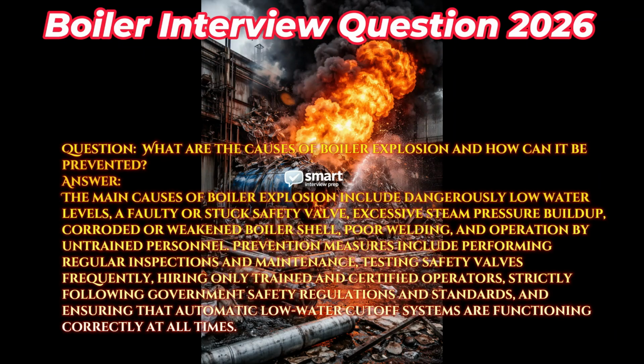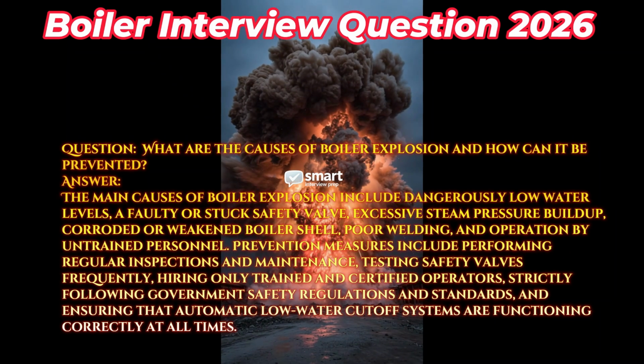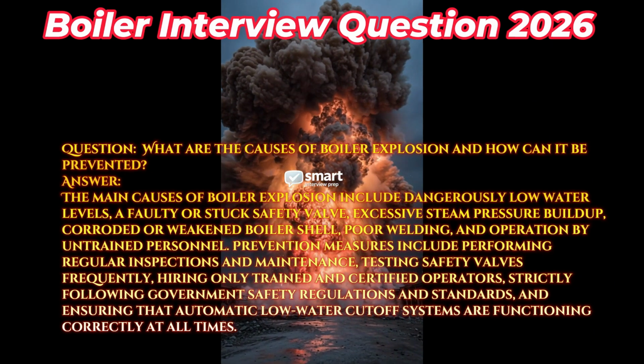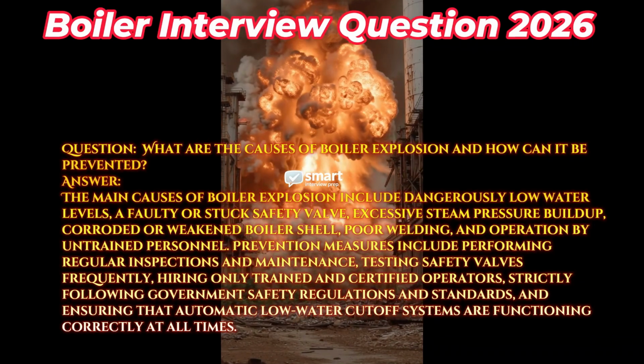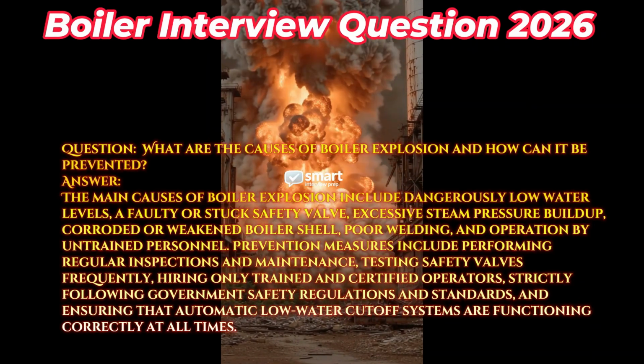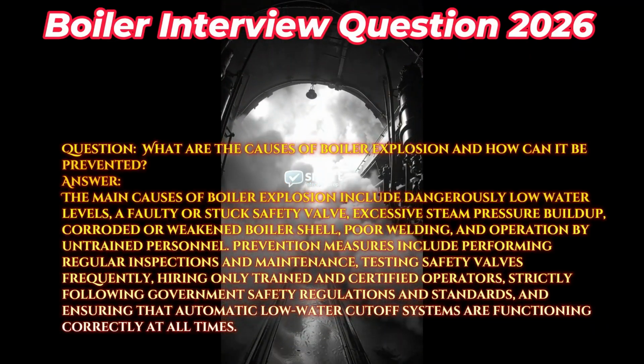Prevention measures include performing regular inspections and maintenance, testing safety valves frequently, hiring only trained and certified operators, strictly following government safety regulations and standards, and ensuring that automatic low-water cutoff systems are functioning correctly at all times.